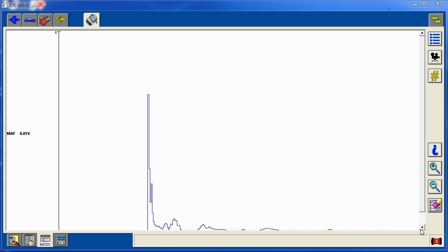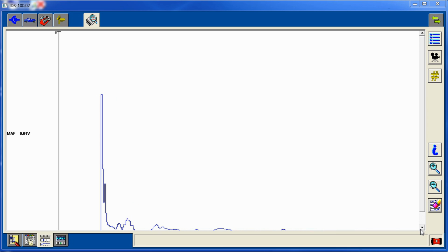Right there. See how it shows like that right there? Any mass airflow sensor should be right around this reading, 0.01, 0.02. And of course, it would be stable if it was inside the airstream there. Moving around a little bit of airflow, it's sensing like it should. Right there, that's the accurate reading. So from this point on, it's going to read at idle, at higher RPMs. It's going to read correctly, and of course, adjust the fuel trims accordingly.